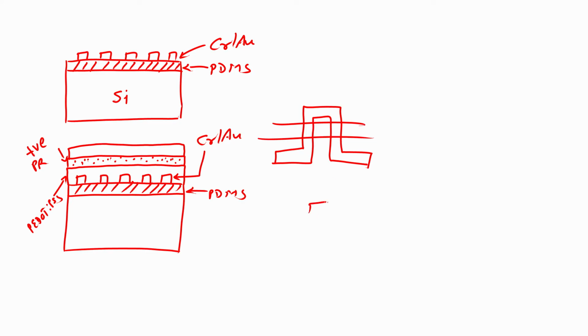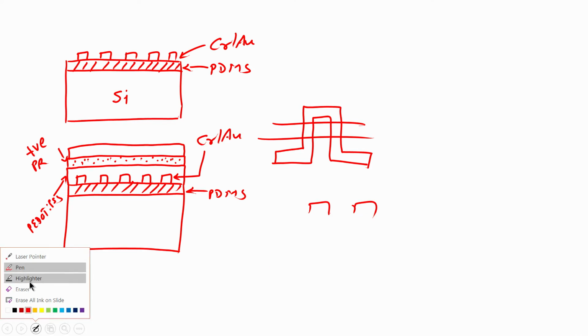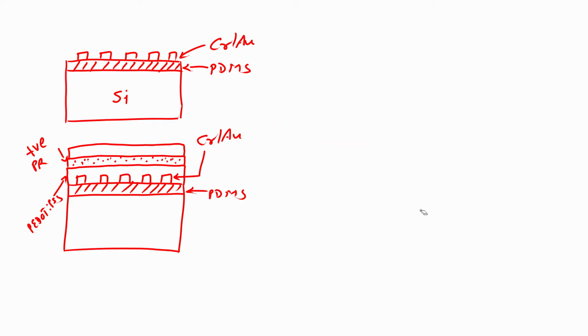If I take a cross section of this particular piezoresistor which is made out of PEDOT:PSS, then the mask that I am showing here will look like this, and this is a bright field mask. The photoresist is positive photoresist and my mask is a bright field mask.